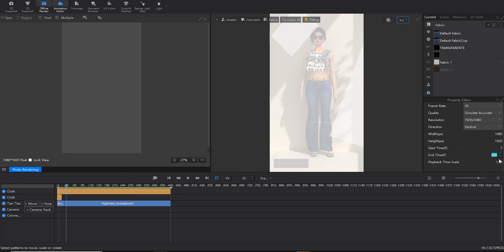And here you can also adjust the start and end time of your animation that the render is going to take into consideration. Since I'm used to working with frames, I usually start after frame 30, that is the transition. The transition takes around 30 frames. So I start around here on the 30. You could just click and select 30, or you could move this green bar by clicking over it and dragging it back and forth. So right here I have adjusted it already.